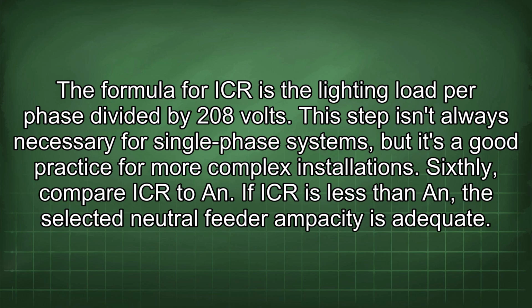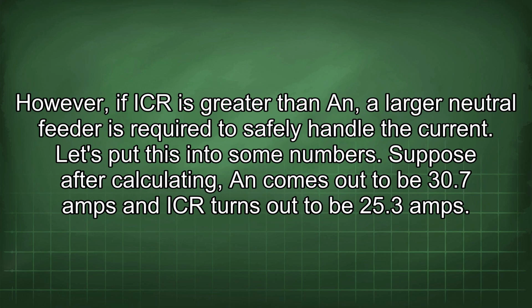Sixthly, compare ICR to IN. If ICR is less than IN, the selected neutral feeder ampacity is adequate. However, if ICR is greater than IN, a larger neutral feeder is required to safely handle the current.